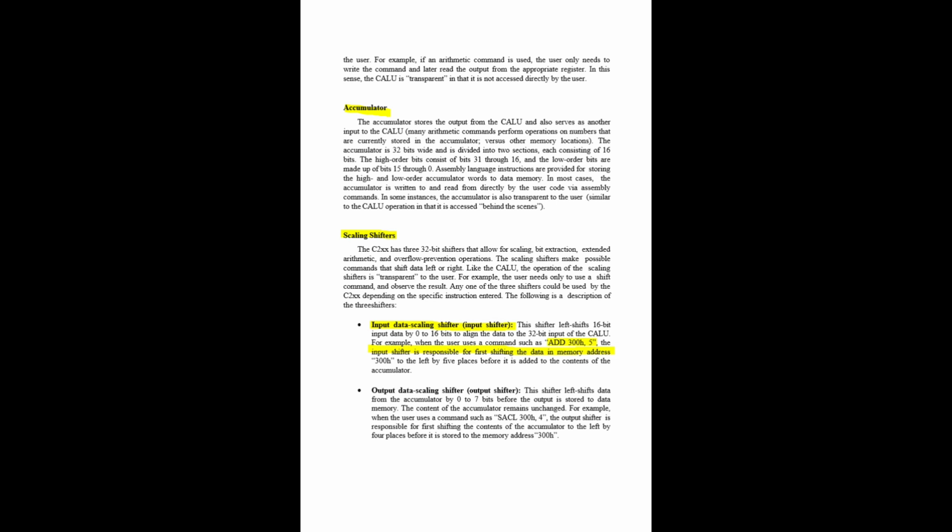Initially, its value is 02. Now, if you shift that value 5 times towards the left side, it becomes 40. You can see that the one will be shifted towards the left side. That means the input value 2 is shifted towards the left side by 5 bits, so that the value becomes 40. That 40 can now be added with the accumulator content. That is what is mentioned.